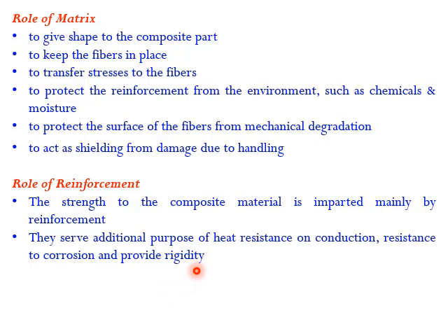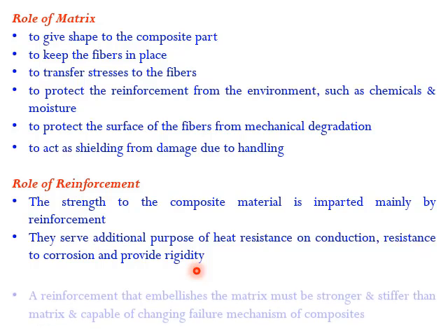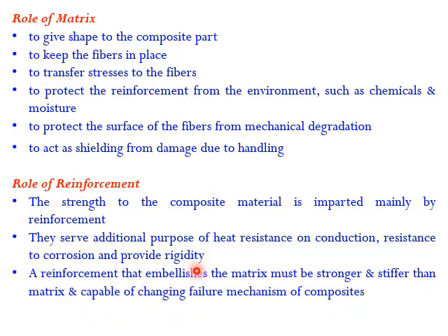If it is conduction, meaning heat transfer through the solid, there should not be much difference in the coefficient of thermal expansion between the matrix and the reinforcement. Otherwise we are going to have dimensional instability.